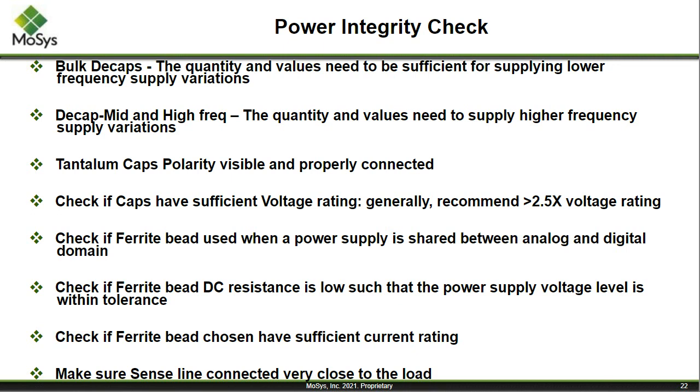The other thing, though, and it's very common in devices that use SerDes, again, you may have multiple power rails, and the power rail that you use for the digital component of the circuit may be the same value. Let's say you have a 1.5 volt supply. You may use the 1.5 volt supply in your digital portion of your circuit, and you could also use it in the analog portion of the circuit.